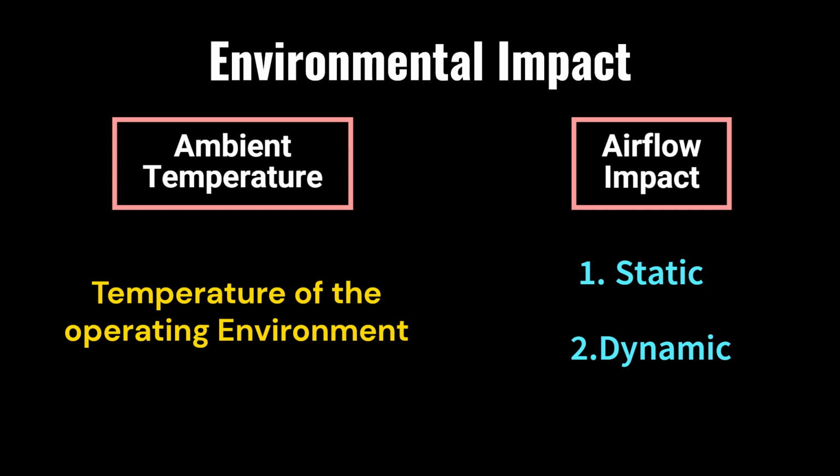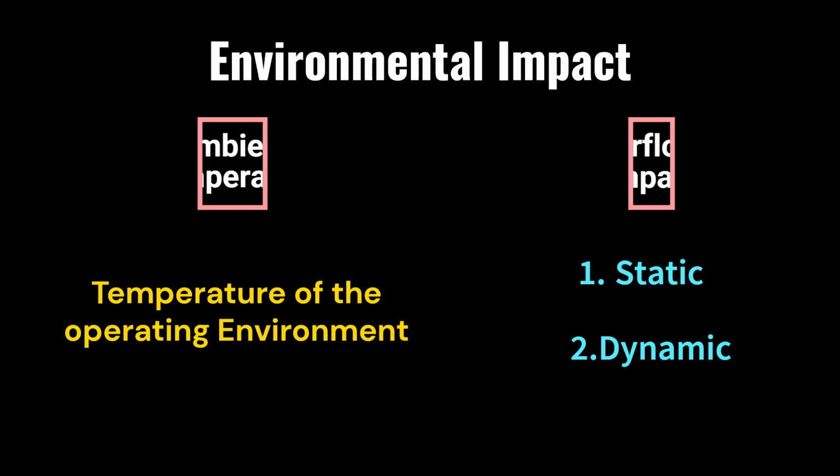Static cooling relies on the natural dissipation of heat, less effective in enclosed or poorly ventilated spaces. Dynamic cooling, for example with fans, enhances heat dissipation and allows narrower traces for the same current. I hope that I have helped you to broaden your knowledge under trace width.